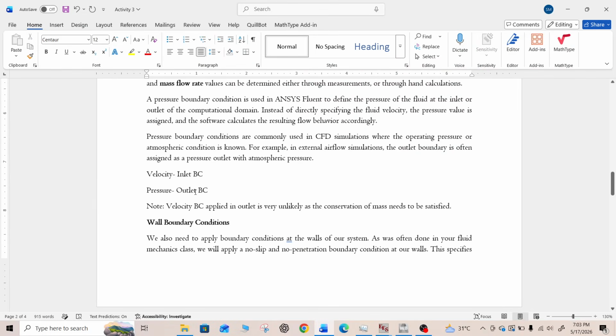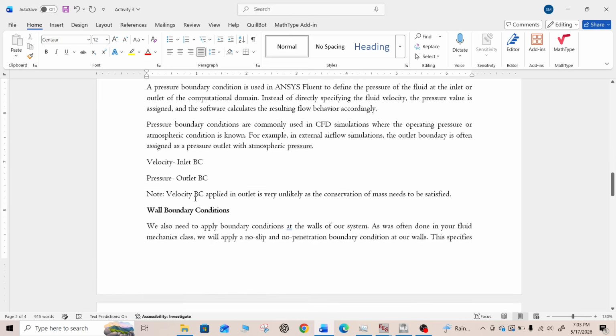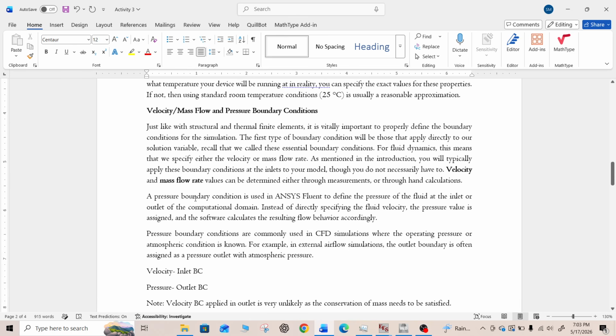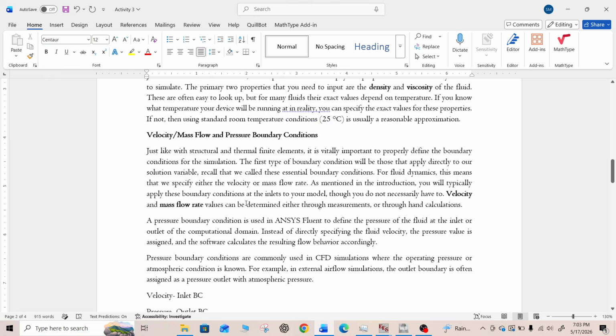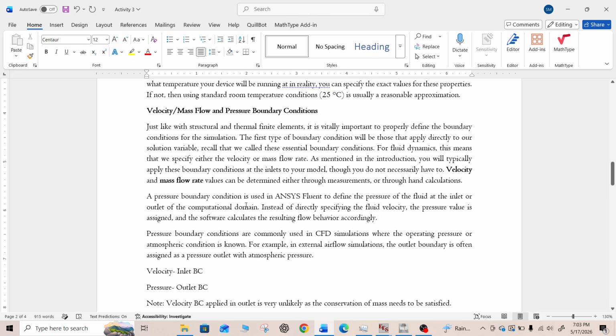Constraint means some faces or surfaces are made fixed so that we can do the analysis. Loading conditions means that an amount of Newton of force or pressure has been applied, and so on. This kind of conditions we had in our structural analysis.